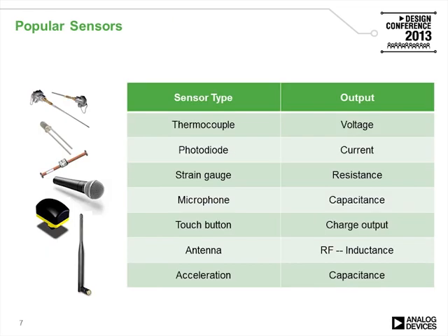There are many types of sensors, and we are so interested in gaining information about the physical environment that we employ many different types of changes in the electrical properties of a sensor. A standard one, of course, will give us a simple voltage, such as a thermocouple, but also we will measure the change of resistance of a device as the physical variable changes, capacitance, charge, any other factor.